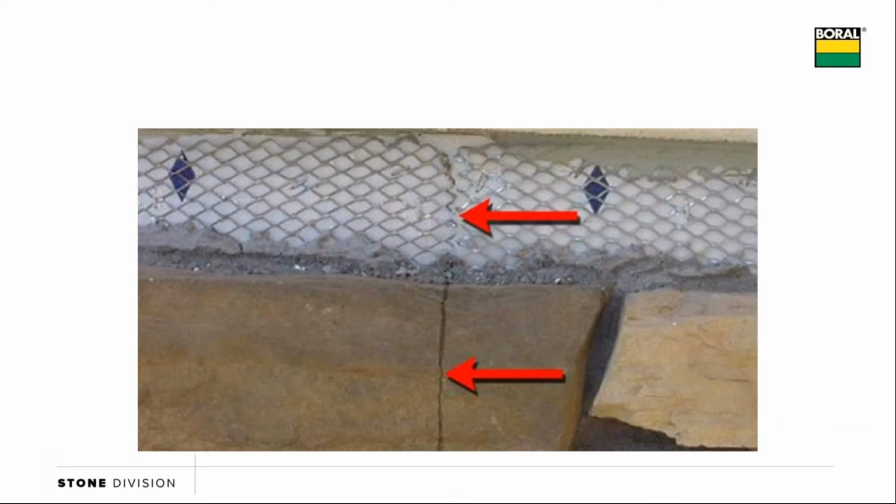In this picture, you can see that the metal lath is not overlapped, and as that wall warmed up, that ends up causing some cracking in the stone. And so code violations like this, or taking things into grade, situations that end up in tear off and repair. So we'll cover a lot of that today also. We'll cover a lot of information. Again, please throw your questions in the chat box.